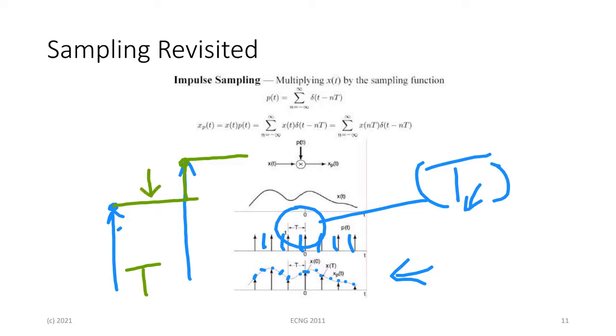How well it does this is a function of the capacitor and of what they call the analog to digital converter, how well it works. If the capacitor is not good, or if the circuit is improperly designed, then between these two points the value may not stay good. Remember, between these 2 points, the computer or whatever it is has to actually get the value. This is just a voltage here. At this point, this is just some voltage. Between here and here, the computer or whatever is going to use that value has to determine what the actual value is.